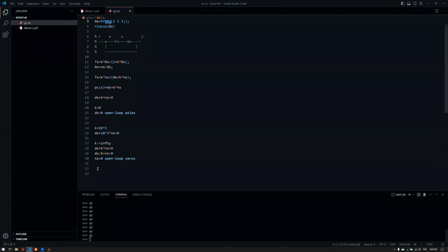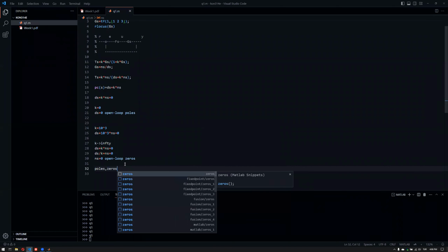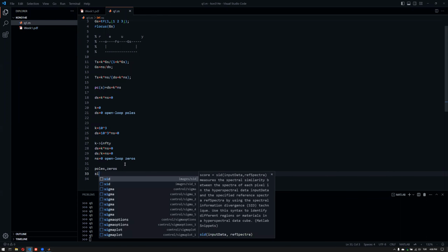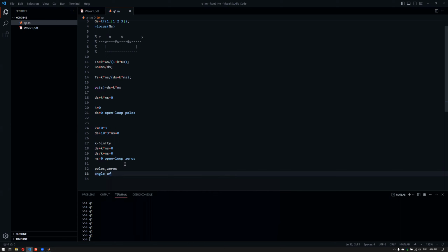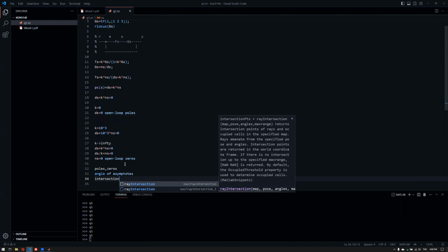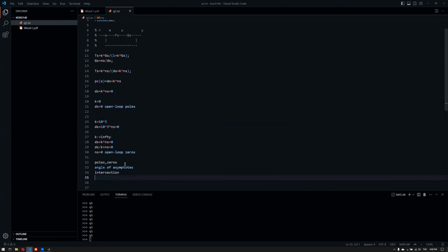And you might recall the fact that plotting a Root-locus plot goes like this. You look for the open loop poles, evaluate the poles, the zeros, and then look for the difference. And then you calculate, for example, the angle of asymptotes, and then maybe the intersection of asymptotes, and then you just evaluate the positivity between the path of the poles, and then try to come up with the Root-locus plot.